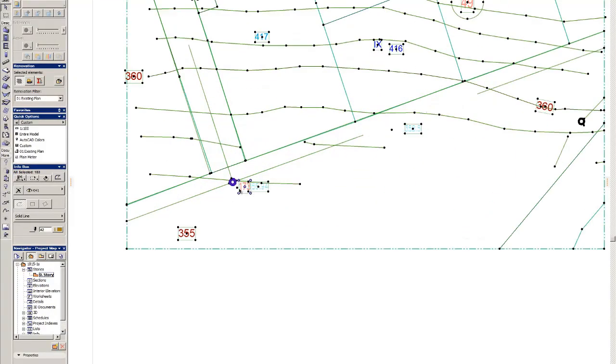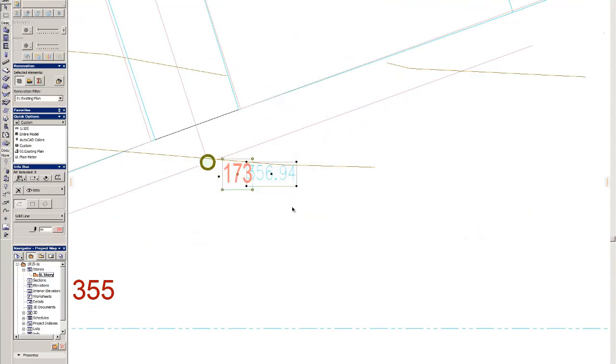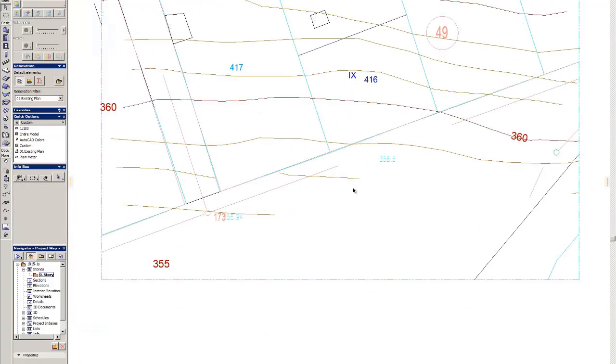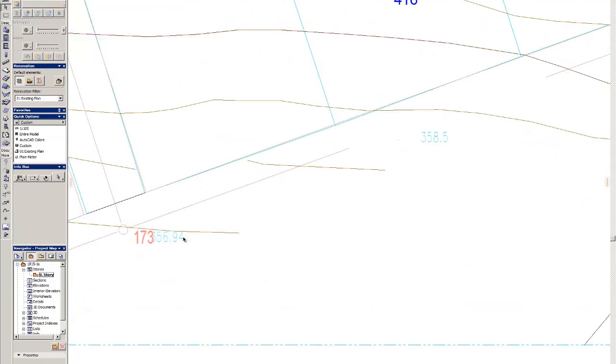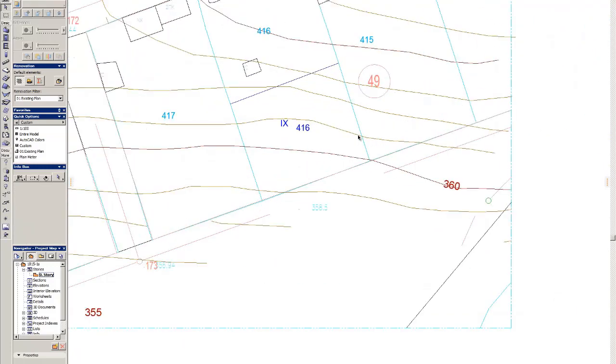After that, we will load that drawing in Archicad. You will notice that all the blocks are imported as groups, and when scaling the project they won't be scaled evenly. That's why before scaling we will need to explode all groups, and we will do that later. Let's copy and paste to our Archicad project.